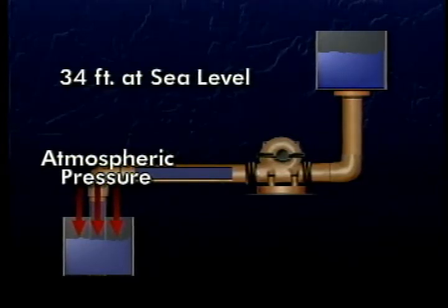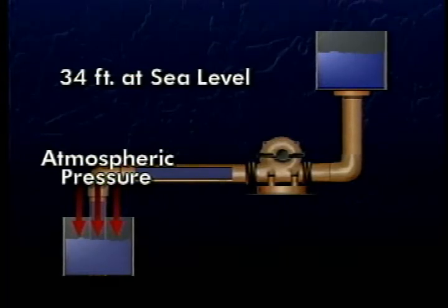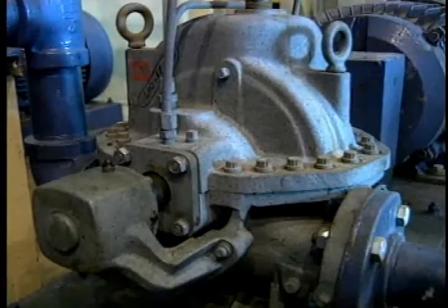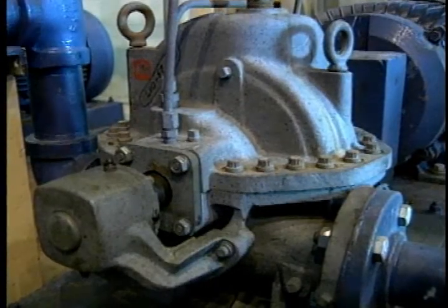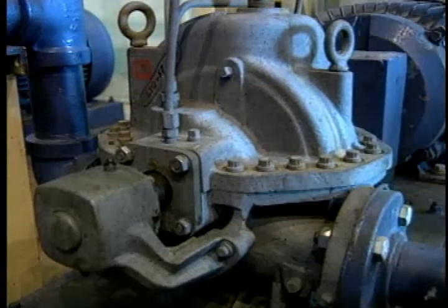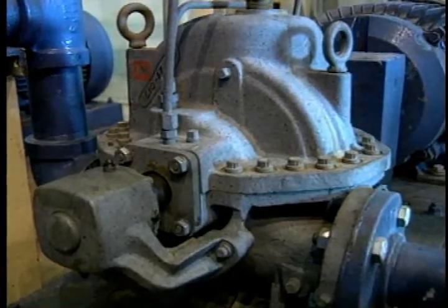So if the suction line is too long, or if the fluid is too heavy, or if the pump is way up in the mountains where the atmospheric pressure is less, the fluid sometimes has a hard time getting up into the pump. Insufficient net positive suction head can cause erratic operation, noisy vibrations, and will probably damage the pump. It may require a redesign of the system.